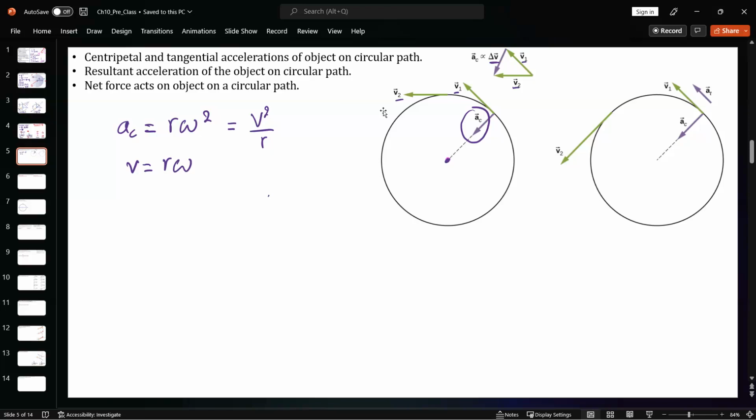We now know the rotational quantities are along the third vector direction. You can see the rotation is counterclockwise. If the rotation is counterclockwise, the theta vector, omega vector, and alpha vector are all in the positive k hat direction, assuming this rotation is on the xy plane.